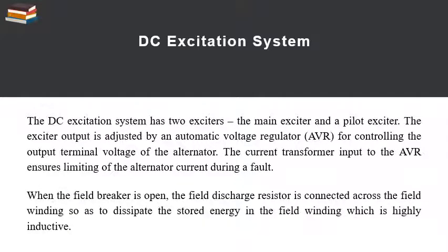When the field breaker is open, the field discharge resistor is connected across the field winding so as to dissipate the stored energy in the field winding, which is highly inductive.